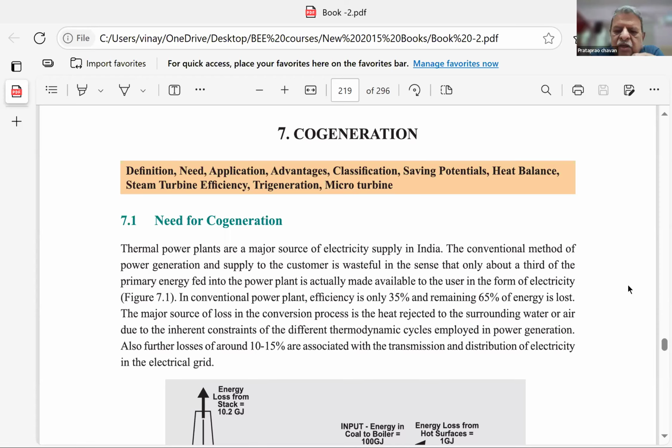So steam for heating is used at multiple levels. Some steam at 120 degrees centigrade with 2 kg pressure. Somewhere the heating need is very light, below 1 kg pressure. Somewhere the requirement is only hot water for the process. So their main purpose of using the fuel is to generate heat.